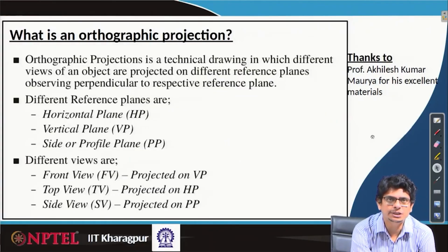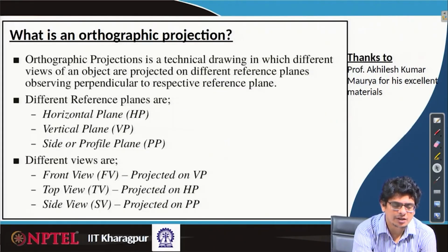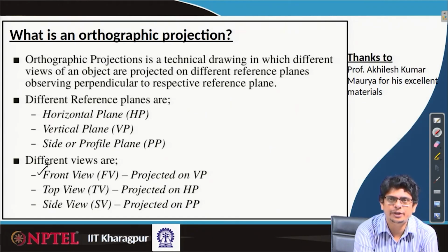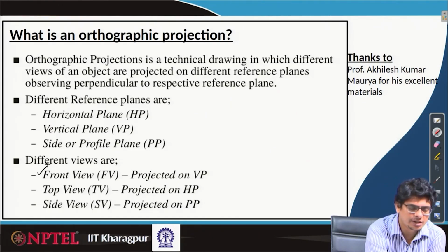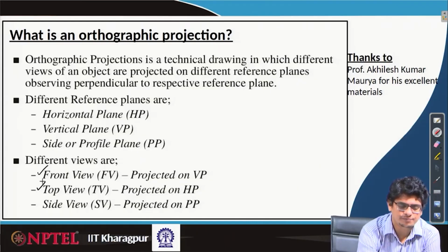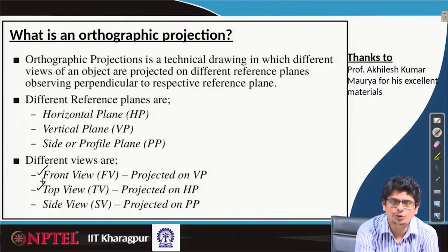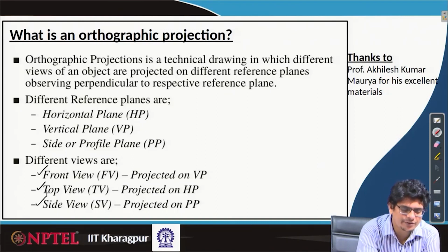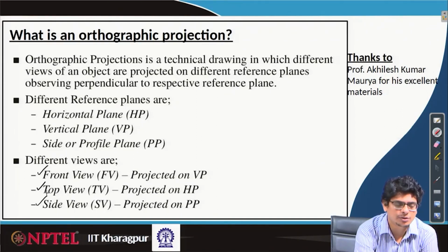The different views of a drawing can be the front view, that means we are going to project it onto the vertical plane, a top view projected onto horizontal plane, a side view projected onto profile plane.